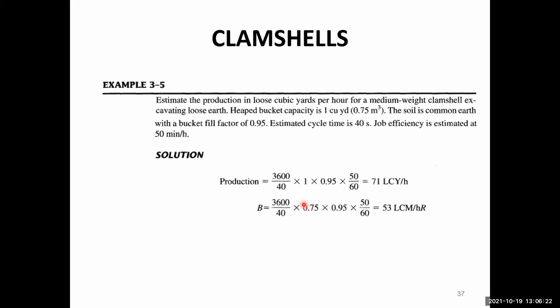There is no swing factor over here because this type of equipment does not need to have any swing, or rather, the swing factor has already been considered in terms of the cycle time. Therefore we are not considering any swing depth factor. So this is the cycle number multiplied by 0.75, and then the bucket fill factor of 0.95.